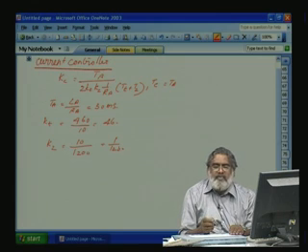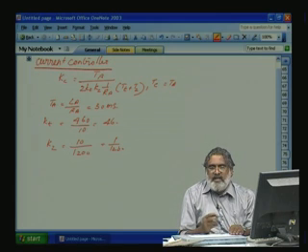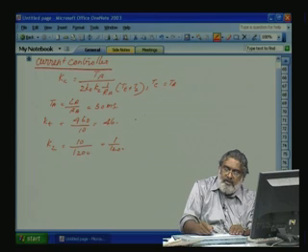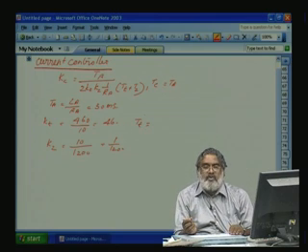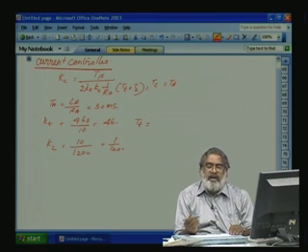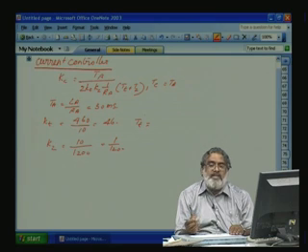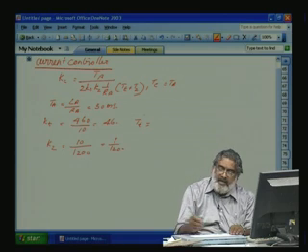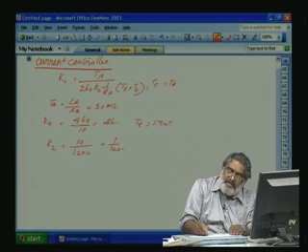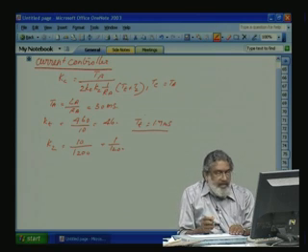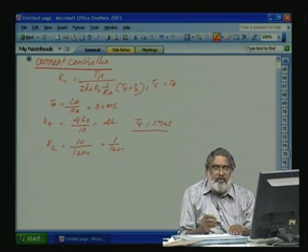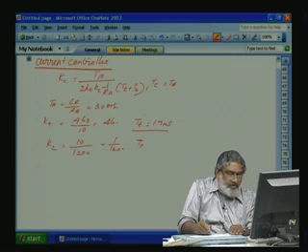Now, the converter time constant Tt. We are using a 3-phase fully controlled converter, so there is a maximum delay of 60 degree, and we will approximate it to 30 degree. For 50 hertz, 360 degrees is the period, so for 30 degree the delay is 1.7 millisecond. That is Tt. Now, T2 is already given, our filter time constant T2 is equal to 3.5 millisecond.